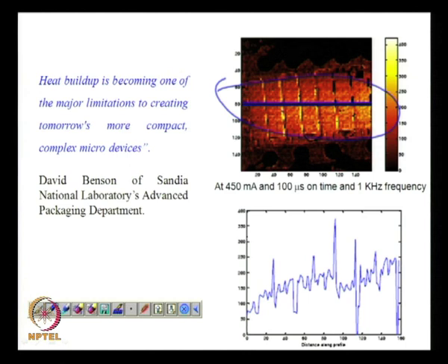So, it is not just a two dimensional problem, it is a two dimensional problem plus there would be variation with time, and there could be transistors or circuits at different levels which are producing heat at different rates. So, it is a complex three dimensional problem, and how you place them is a major concern of VLSI design. Now, we are presently working with some sort of a rule of thumb. It is more of an art than a science. We know which is going to be the most heat generating component, and we would like to place it somewhat separated from the others.